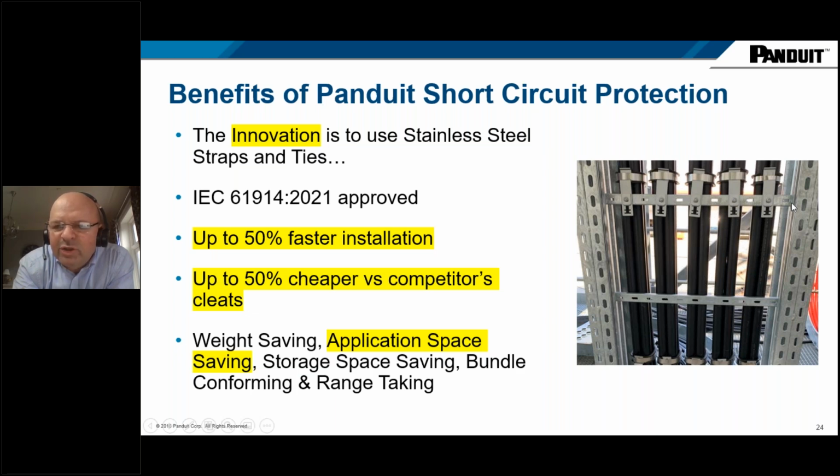So they are able to populate more banks of cable in this width of ladder rack than a traditional cleat, which would have to be fixed here and here, for example, which means the next time you try to fix it will be here and here, which means that in reality, you could probably only get 3 banks of cable into that size of cable containment.